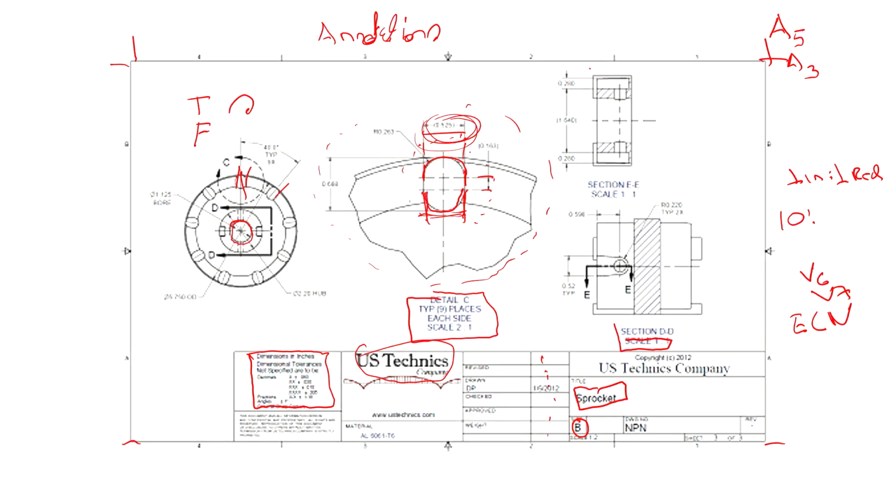Another rule of thumb is that you always want to keep them as aligned as possible. This is just a tool that every CAD has so that it's easy to follow. And you want to avoid as many annotations crossing the geometry as possible. So this one right here will be a no-no, but there's really not much room for anything else unless you had another section somewhere else where you put this one and then this one could be over here. But definitely a rule that needs to be followed is that you can never cross annotations. You're trying to avoid crossing geometry, but it can be done.